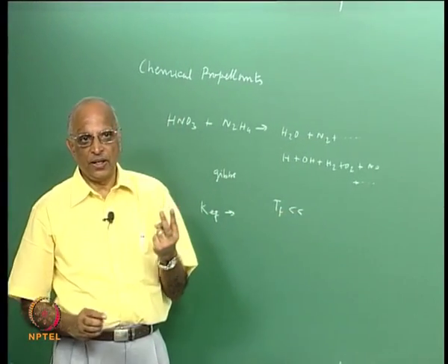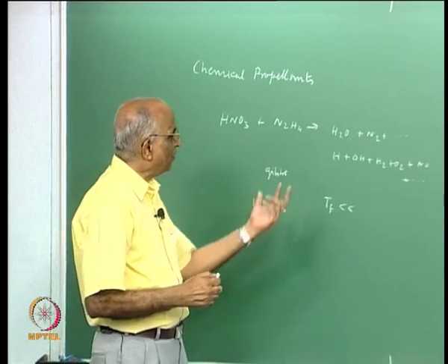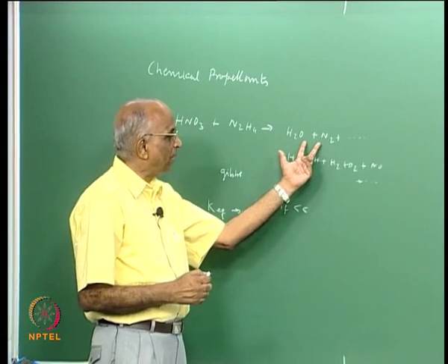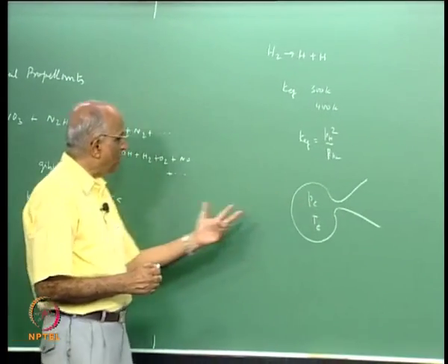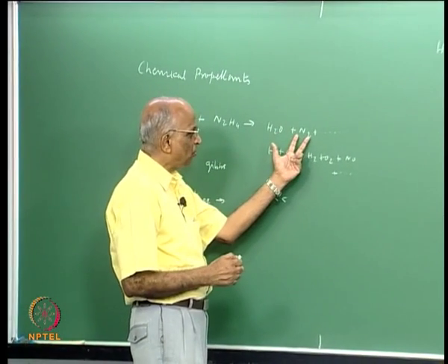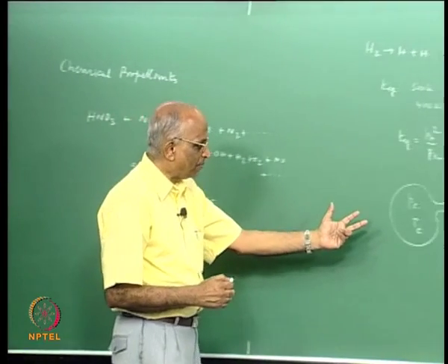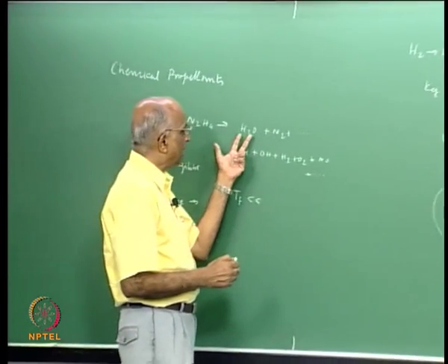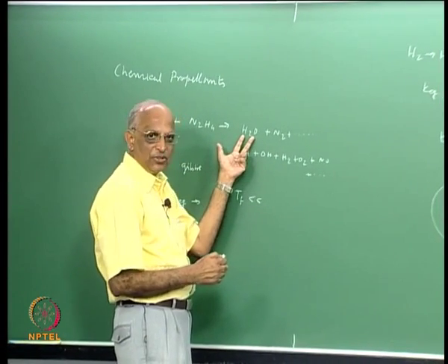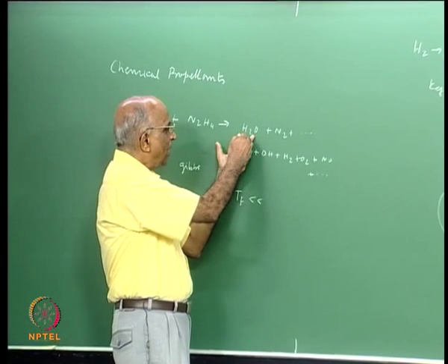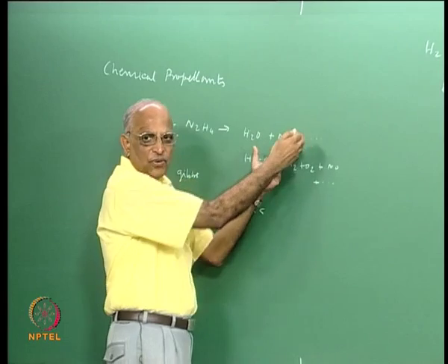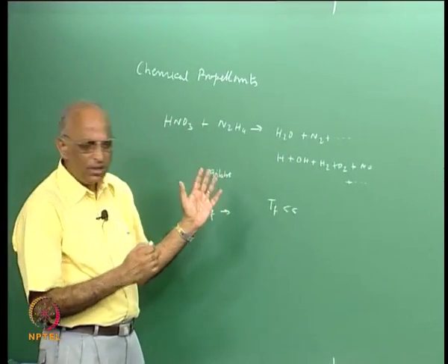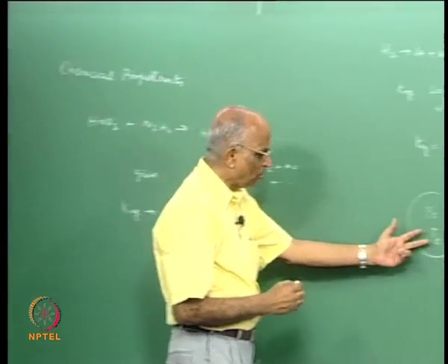We decided earlier, we said, well, if it is stoichiometric I will have completed combustion products and I can calculate the value of Q. Once I know the value of Q, I know the specific heat distribution, and therefore I can calculate the temperature. I can also calculate the phase changes, the temperature change from the initial value to the boiling point at that phase change, and again from boiling temperature to flame temperature for each of the cases. Therefore, we know how to calculate this for stoichiometry.